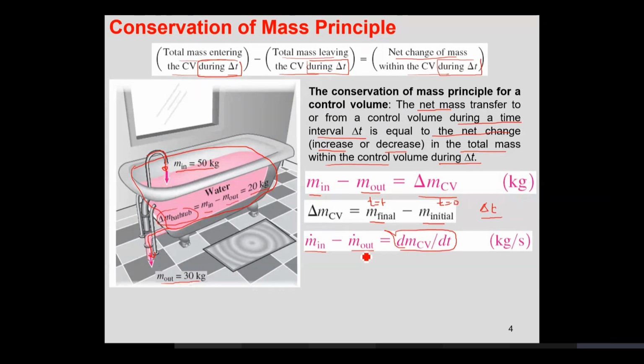Now, can you tell me, let's say I have this pipe over here, and this is the cross-sectional area of the pipe. There is some fluid flowing out of the pipe. The area of this cross-section is, let's say, AC. The velocity is V average, and the density of my fluid is, let's say, rho. So can we express the mass flow rate in terms of these three factors?